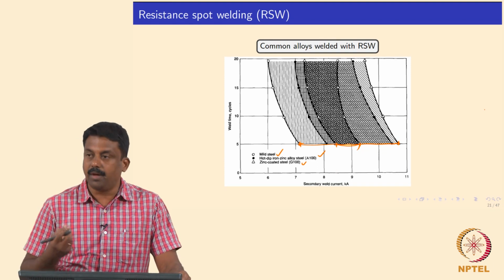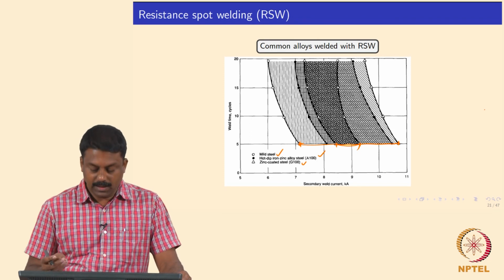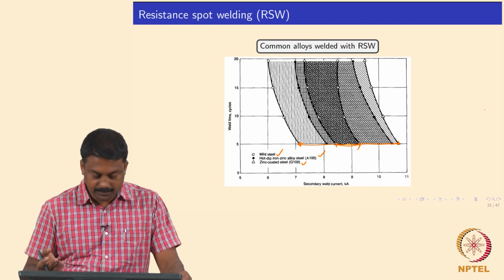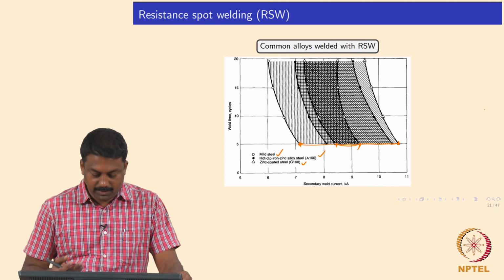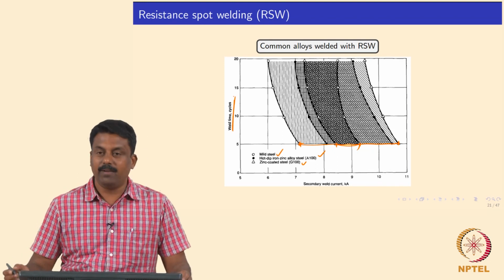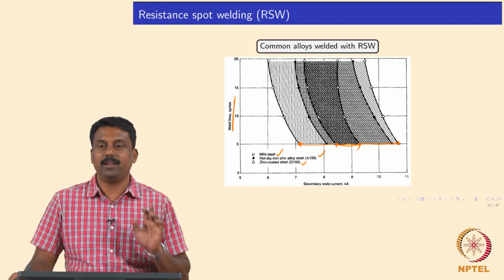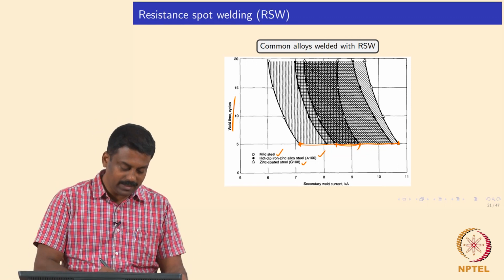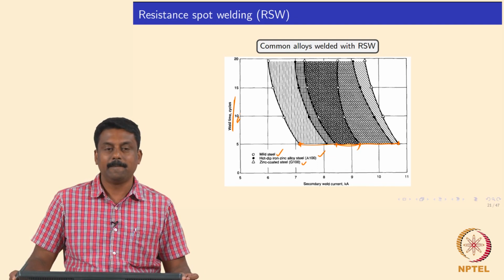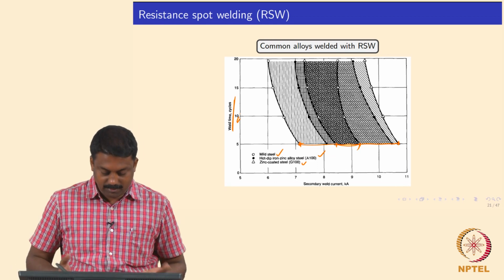So you have to soften the galvanized layer. You need to pass a ramping current so that you soften the zinc coating layer, and by doing so you also increase the weld time in cycles. You see that weld time in cycles. You never give weld time in resistance spot welding in seconds. You always mention it in cycles. For example, 10 cycles means 200 milliseconds. Okay, it's clear. So we generate such a curve.